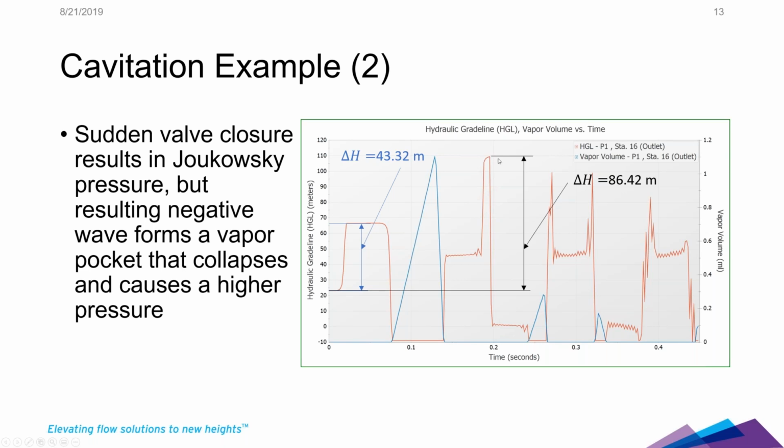Let's keep going. Yeah, and I think based on their measured data, their measured pressure spike was close to 100 meters, or head spike. We're talking about head. In this case, a lot of the academic papers, a lot of reference materials use head instead of pressure. It was about 100, so this is 110. Okay.